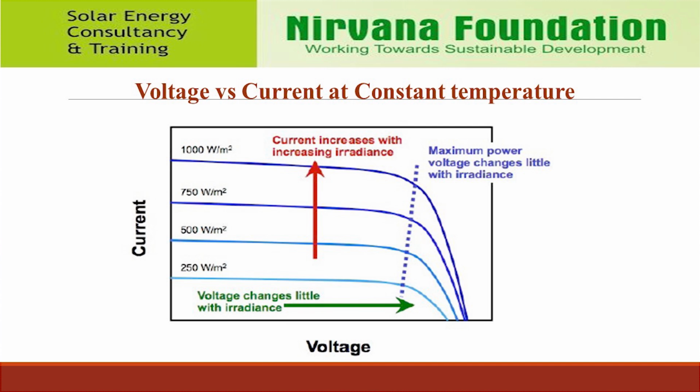A higher irradiance level is more beneficial than higher temperatures when it comes to power output. Ideal conditions would have a very high irradiance level and low temperature, but unfortunately such scenarios are very hard to achieve anywhere in the world, as solar irradiance levels and solar temperatures are very much so dependent on each other. You can see from the illustration that this module loses voltage as the cell temperature increases. That effect is common to all crystalline modules.